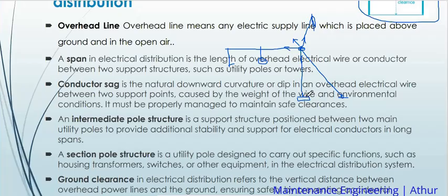And I think it has a formula. If I still remember well, for a normal stay, if it is LV, then it is how much? Is it 3.3 meters? 3.3 meters from the pole here to where the stay is. That is supposed to be around 3.3. Because the formula of getting it is 1 over 3, a third, times the height of the pole.